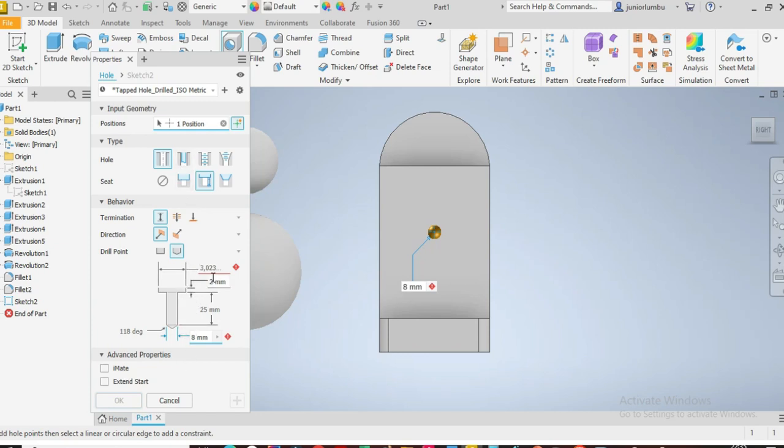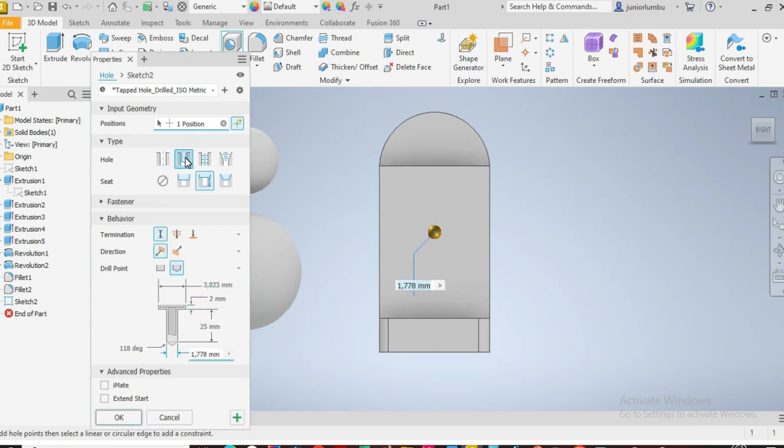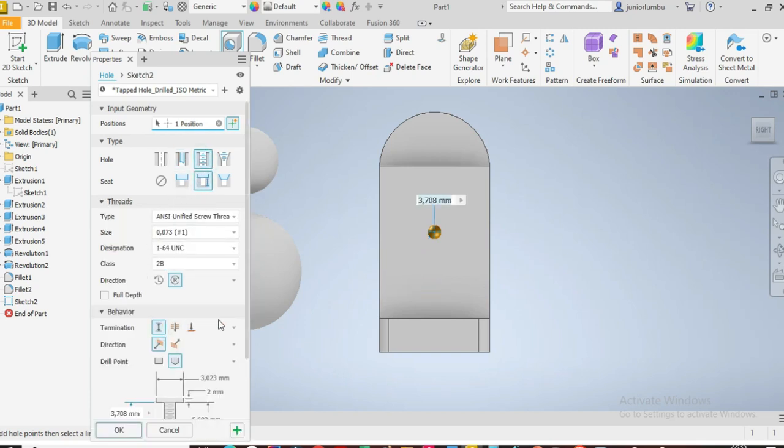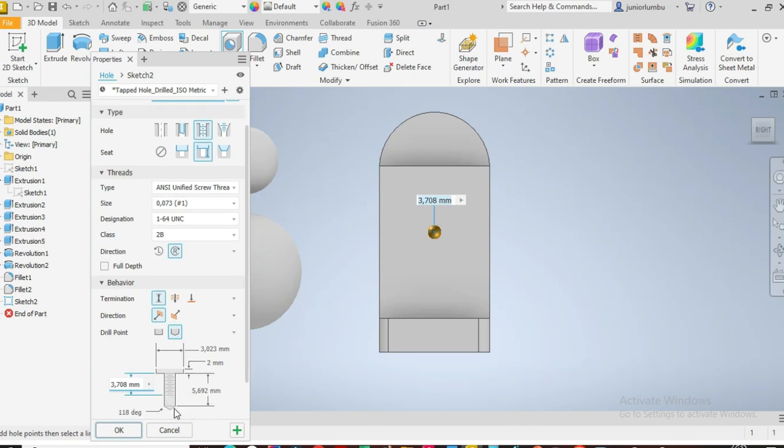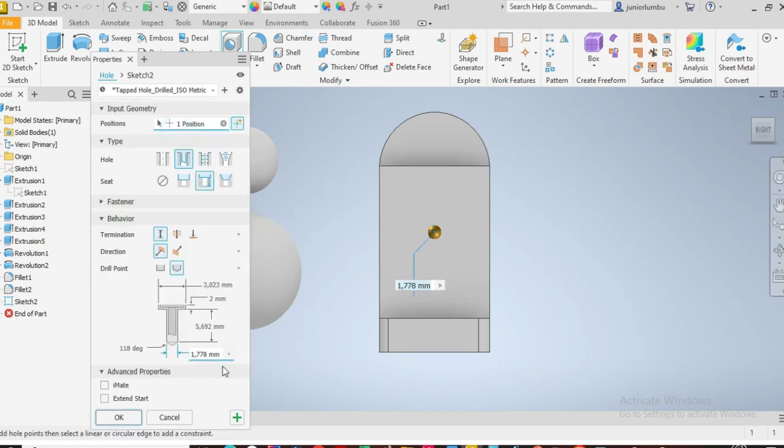So with this, you can reduce your step there. You can say 0, and then the step will be removed. So you have that hole. This one here is with thread, so you're going to have to choose with thread, but you're going to use this simple hole. So I'll come here, I say, okay, cool, how big do you want your step to be?